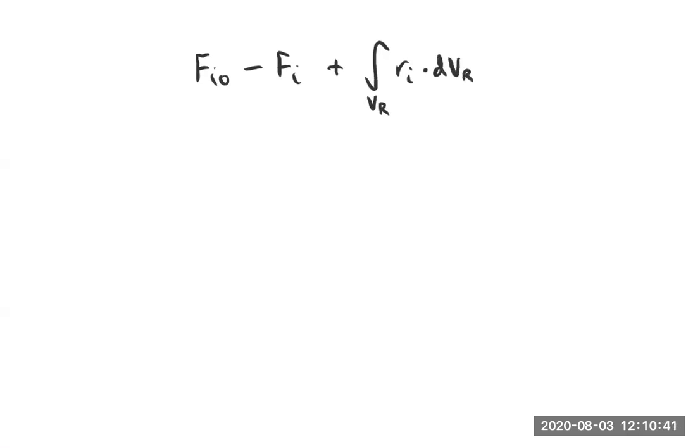And then our accumulation remains what it always is, dNi/dt. Actually, the convenient thing about a plug flow reactor, like a CSTR, I don't know if I included this as one of the assumptions, but it's at steady state, and so at steady state dNi/dt equals 0. So that's convenient.